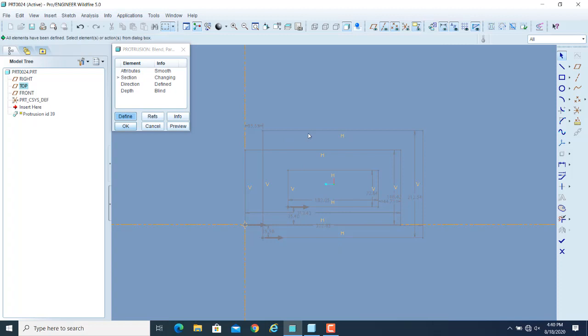This is because we were in the last section, and after the last section when you toggle, it will give you an option to make a new profile or sketch over here. So you can insert new sketches also. Without going for any sketch command, if I again right click and choose the toggle section option, it will then select the first one.